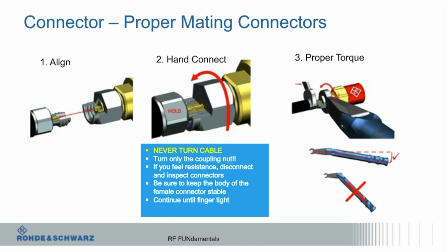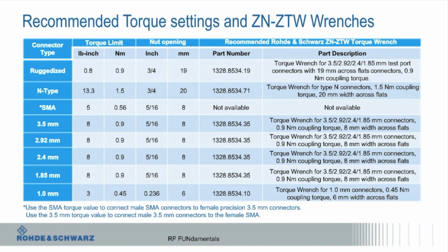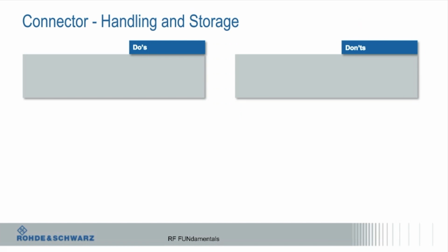And again, this is especially for VNA stuff. See, there's a Cal standard on there. So the Cal standards you'll even find, particularly if you get above probably 18 gig, if you don't torque them, you're not going to have a repeatable calibration. Okay, kind of beating this to death. Here's a bunch of different wrenches and what the torques are. I'm not going to quiz you on that because I don't even remember them.